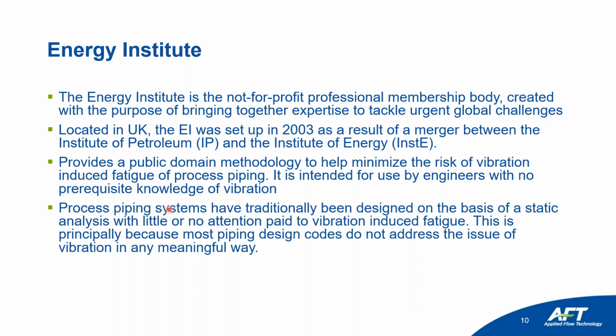As we know, process piping has traditionally been designed on the basis of static design. So what we do is a stress analysis and lay down the supports to comply with B31.3 or B31.1 or B31.4. But we pay little attention to vibration-induced fatigue.